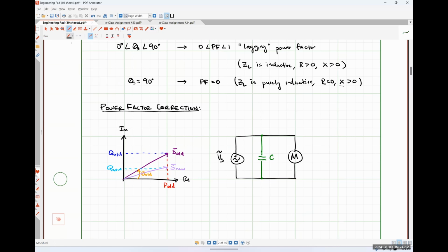So drawing this as a more realistic representation, we might have some transmission line impedance Zw equal to R plus jX. So placing our capacitor in parallel with the source corrects not only the power factor problems caused by the inductive motor, but also any inductance contributed by our transmission lines as well. Okay. So let's talk about what's going on with the math here effectively.